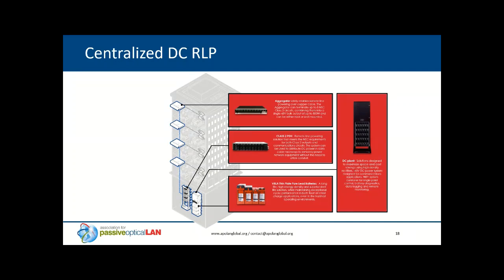Obviously, that's centralizing it. You're going to have freed up CapEx and freed up OpEx from less equipment and less management and maintenance after the fact. An example of this that Chad showed earlier is a drop-down ceiling box. There was a splitter, there was a power system, all in that drop-down ceiling box that was being fed from a Class 1 circuit from a centralized plant. Obviously, you couldn't fit a UPS and a DC plant or batteries up in that ceiling drop-down box. So in this case, we just run a Class 1 circuit to it.